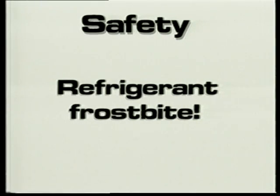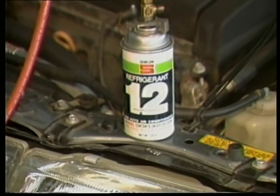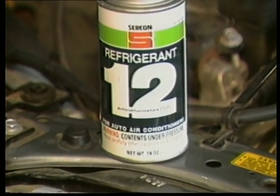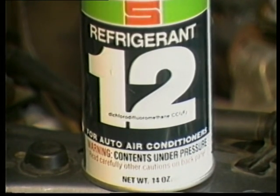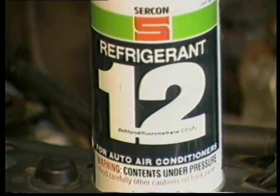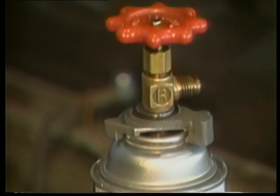Always think safety when working. Refrigerant can cause severe frostbite. If it sprays out of a ruptured or loose fitting, it can produce painful burns to your skin and eyes. When liquid refrigerant leaks out into atmospheric pressure, it instantly begins to boil and vaporize and can freeze skin tissue. For this reason, always wear eye protection when working around an air conditioning system.